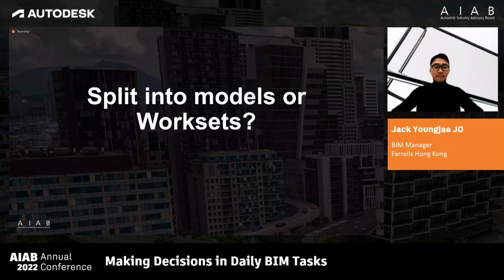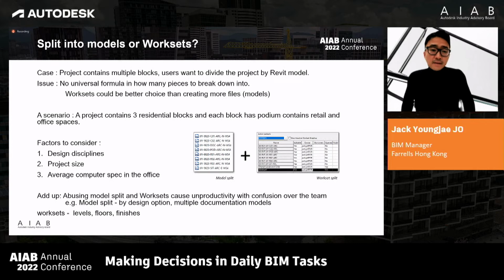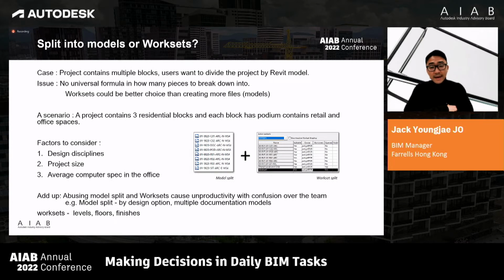The second topic is split into models or work sets. The case is that a project contains multiple blocks and the user wants to divide the project by Revit model. But the issue is that there's no universal formula for how many pieces to break down into, or whether they need to break down into work sets or into models.